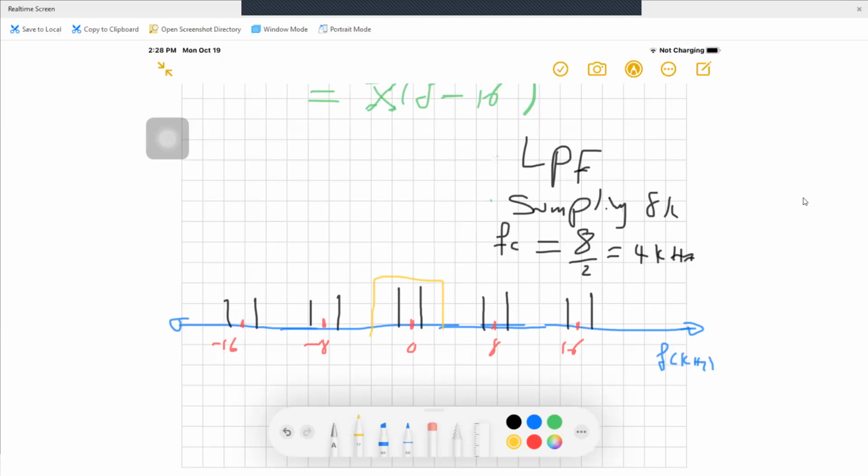Yeah, again, according to the example requirement, they asked us to draw the spectrum up to 20 kilohertz, no more. So if I'm going to take more delta f's of the sampling function, 0, 8, 16, the other one will be what? At 24. 24 exceeds the 20 kilohertz. So again we are limited by the problem requirement, which is 20 kilohertz, no more. Any questions? Of course. Continue.